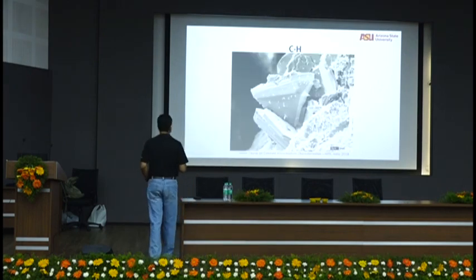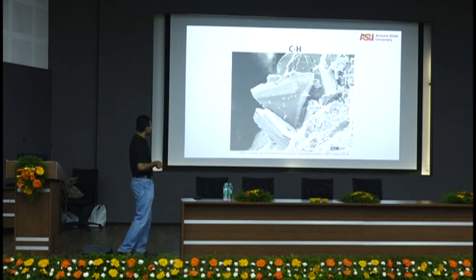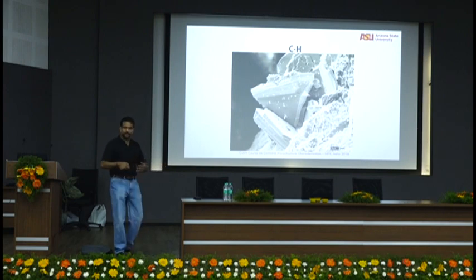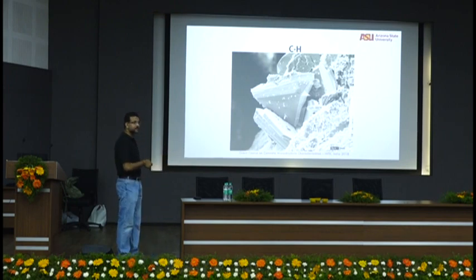So that's calcium hydroxide. If you look at sheets of calcium hydroxide, you see all the sheets forming on the surface of a hydrated cement particle. And this side, what is this? There's a big capillary pore right next to it, right? See the layers of CSH, and typically you can see large masses of CSH forming, because when one nucleates and forms, that acts as the surface for the next one. So sometimes you see layered CSH structures.